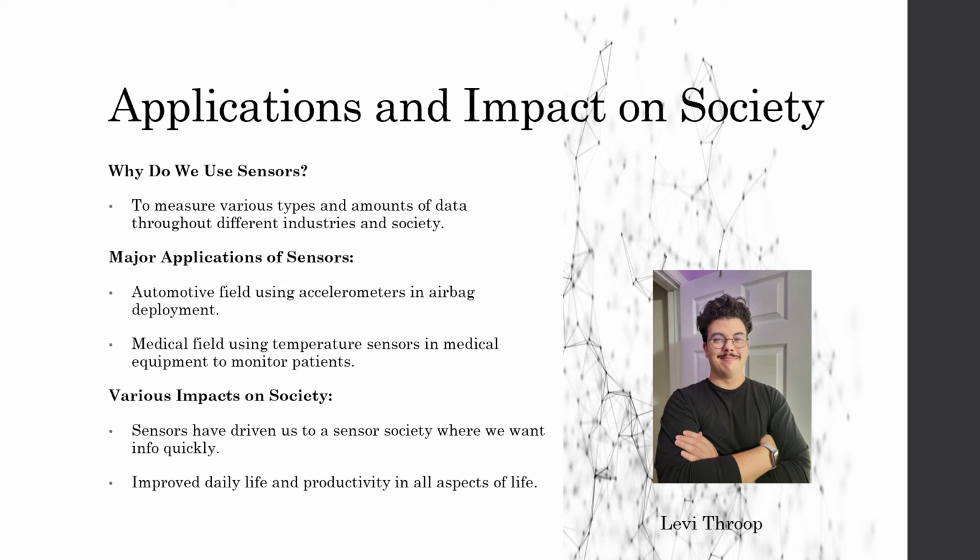An accelerometer, in summary, is a sensor that can measure the acceleration of motion of a system or structure. When acceleration acts on the sensor, the material is compressed, which produces an electrical charge that can be converted into measurable quantities. One of the most important usages of these sensors is in the automotive industry. They are used in airbag systems, and when the force of acceleration or movement passes the limit threshold, it can signal the controller system to deploy the airbag, potentially reducing damage to the operator and passengers of the vehicle.